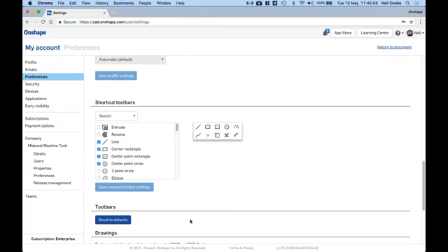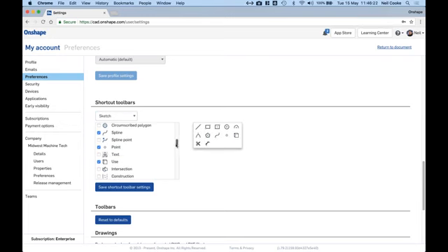And one of them is the S key. If you've ever used the S key on SolidWorks, it's just a quick way to bring up a shortcut toolbar next to your cursor for your most frequent commands. So the same can be done in Onshape. So you can see for sketching, or for parts, assemblies, or drawings, you can create a different shortcut toolbar. So if we're in the sketch and we use a conic a lot, you can add the conic to the toolbar, polygons and so on, or take things out.